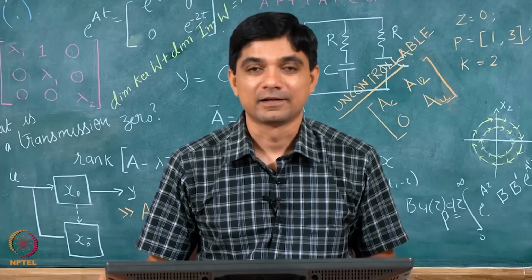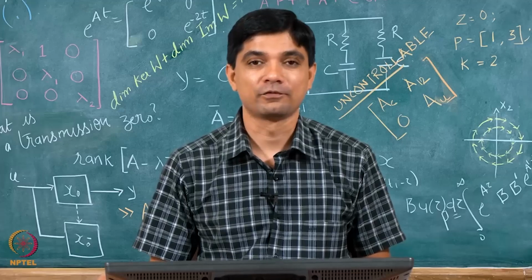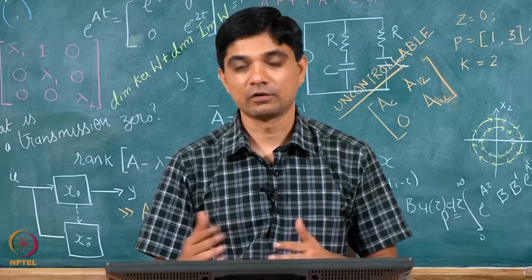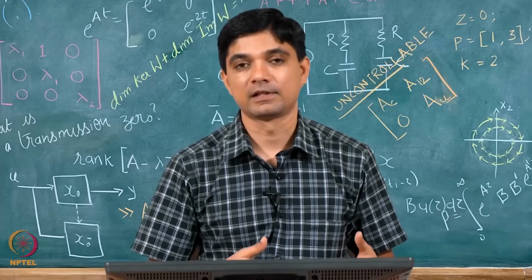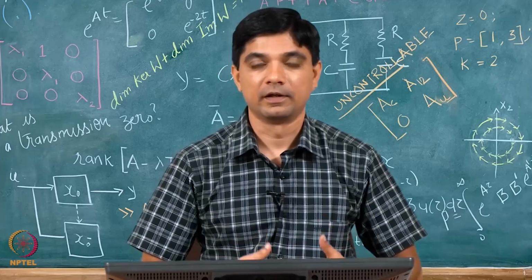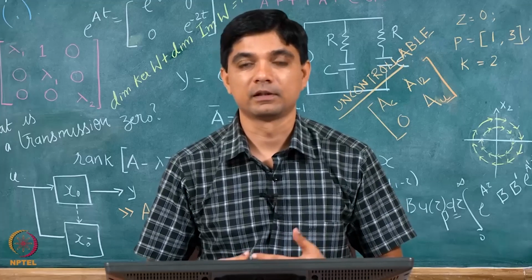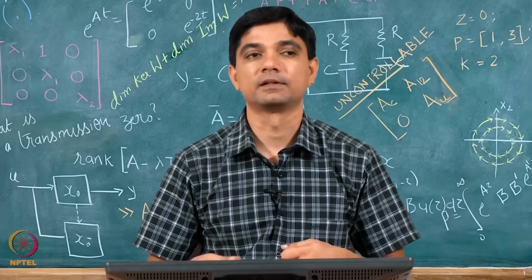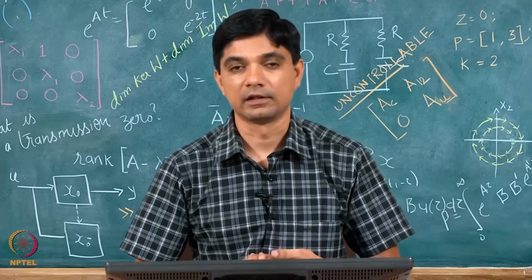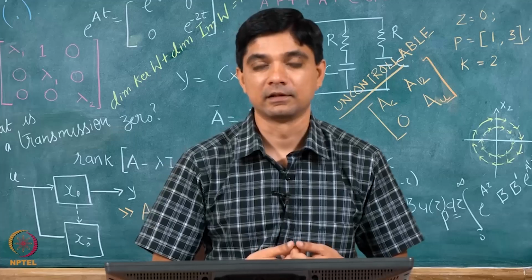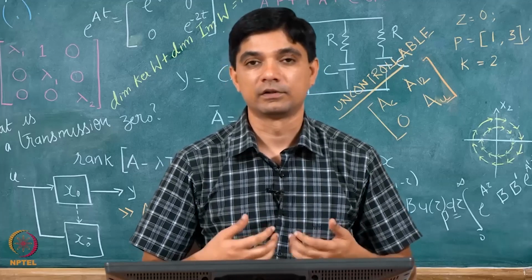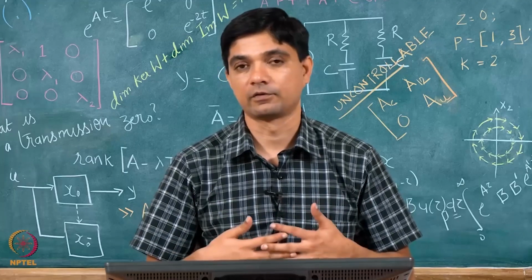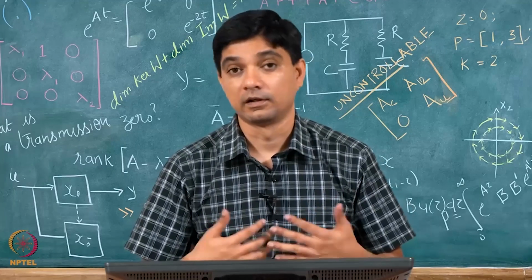Hello everybody. Welcome to lecture number 2 of week 11 of the course on linear systems theory. As we saw in the previous lecture, we redefined our control problem in terms of certain optimality conditions to be fulfilled, and then we had a couple of methods to derive conditions for what we call the LQR controller, which essentially ended up in solutions in the form of an equation called a Riccati equation.